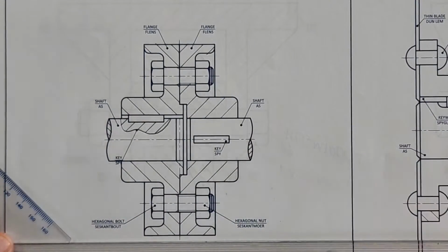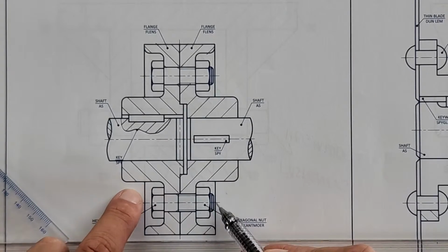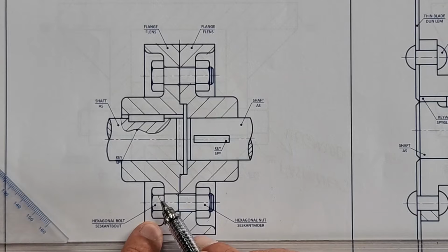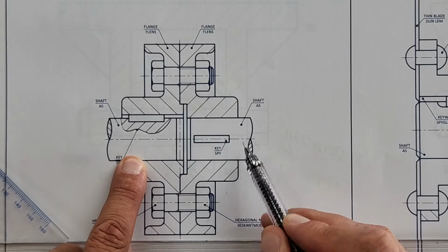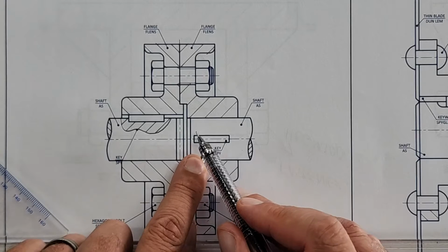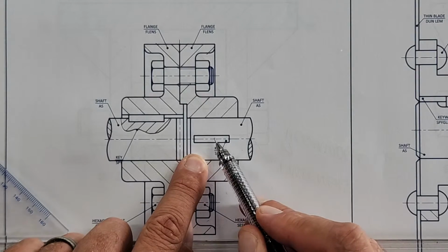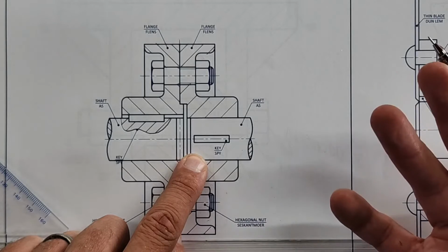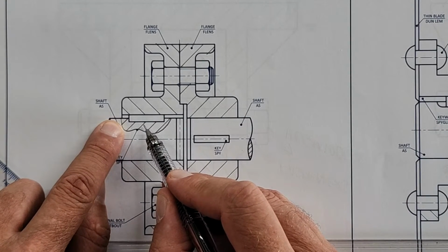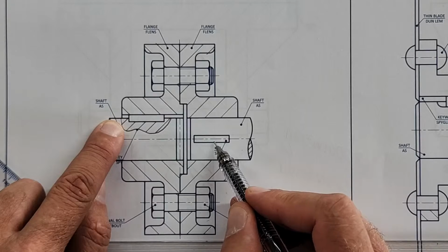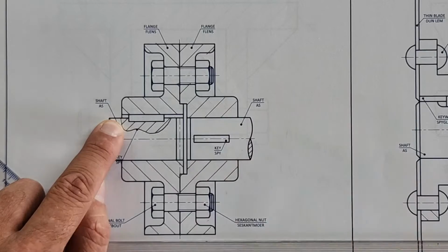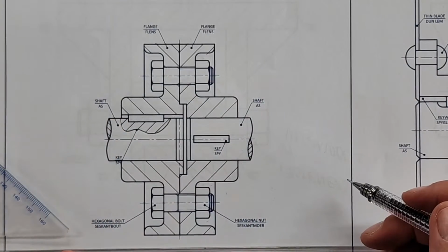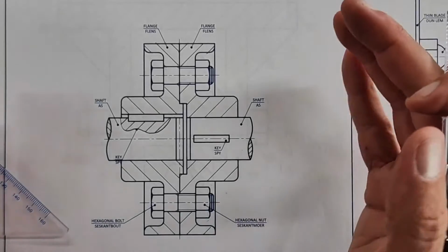Okay, what part am I missing now? Okay, air parts, of course, that we're not going to hatch. We're not going to hatch the bolt, also not the nut, not the shaft of this bolt. Here we have another shaft. This key now, if I would section this part, do a partial section, will that give me more information? Will it help me? No, it's only here that it does help me. You see that? That's why here I can do it, but I'm not going to do it here. I'm not going to do the key, not the keyway either. There's another air cavity here, not going to do that. Same on that side. So that's basically the fullness of this flange assembly.